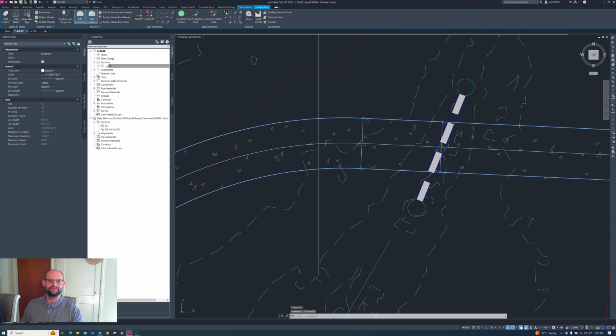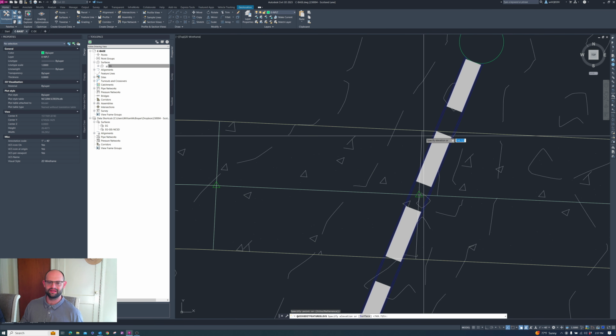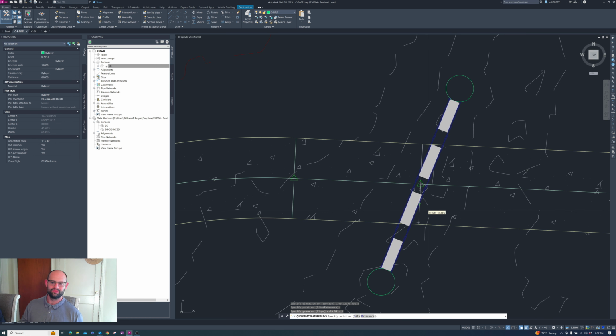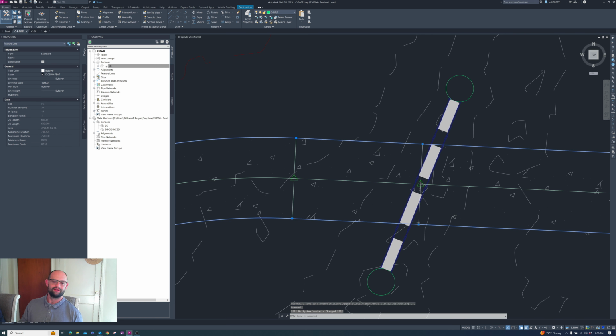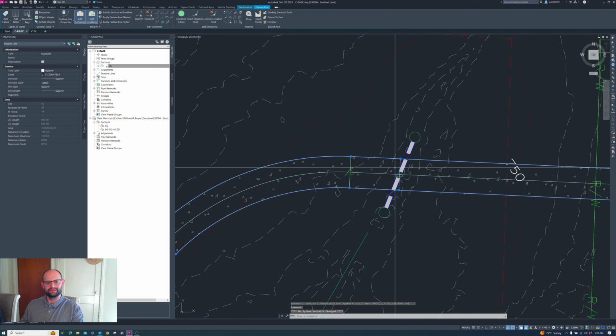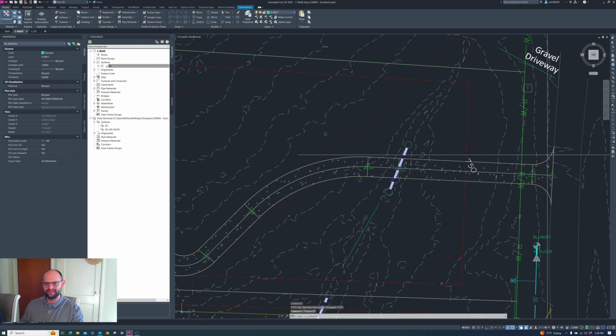So we will use the quick elevation edit button up here. Click this vertex and assign that number we just came up with, 751.5 to here. We will work up at 2% to generate a normal crown. We will go back down at -2% away from that center line. So we have a key point set here and a key point set here. We're going to set a smooth slope between those two. We'll go ahead and assume this is going to be a low point in the road.